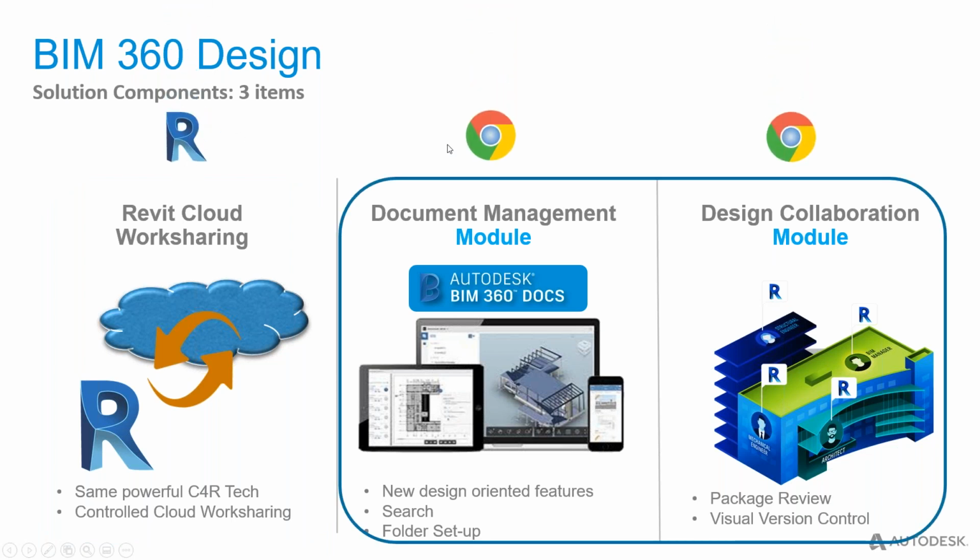So you'll see this one sits in Revit. These two are cloud-based. This is the actual BIM 360 Design module in the cloud. I'll give you a screenshot later on. This is the official handover process through what we call packages between the different disciplines. So as I mentioned, yes, the technology is still Revit Worksharing, but there's a lot more to it to get to that official handover process between different disciplines.